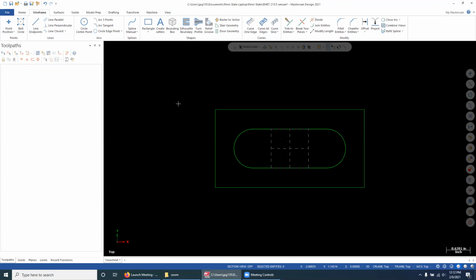And specifically putting in dimensions. So I had entered a width of 3 and a height of 1. So in Mastercam, just to show you what that means in terms of an ob round, because there are better ways to dimension ob rounds if you're doing an engineering drawing. But again, here the purpose is more to use this as my place to do a slot mill, because this is a very familiar shape for slots in machining.